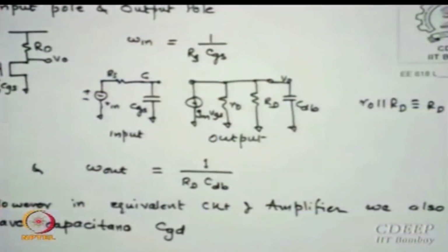Okay. So let us look at a typical common source amplifier. Whatever is true for common source is true for common gate. Once you draw the basic equivalent circuit, everything is identical for us. So the example is only shown for a very trivial common source amplifier with a resistive load. If there is a current load, what will happen? RD parallel 1/gm or r0 parallel, whatever it comes, the corresponding loads will appear. As of now, RD represents the load, whichever way you create it.